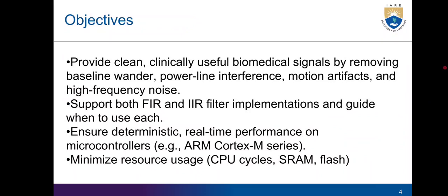Objective: provide clean, clinically useful biomedical signals by removing the baseline wander, power line interference, motion artifacts, and high frequency noise. Support both FIR and IIR filter implementations and guide when to use each. Ensure deterministic real-time performance on a microcontroller, for example ARM Cortex-M series. Minimize the resources used: CPU cycles, RAM, and flash.